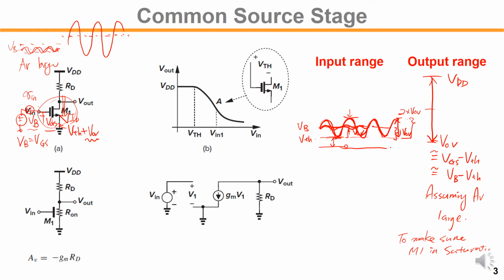So our purpose is to maximize the output range, because the gain is large, so the output swing will be very large in this scale. So we want the output common mode level to be between those two. So we want to design the output VOCM to be half of the VDD plus the V overdrive of the input.